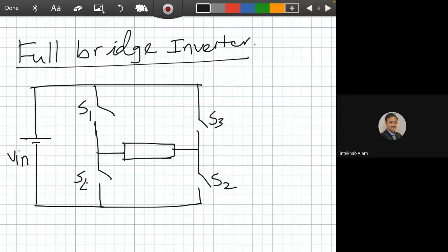The frequency here may be like 10 Hz, 50 Hz, 100 Hz, but in the chopper circuit, the frequency may be 0.01 Hz, each 10 seconds or something like this, or maybe more or less. Exact. Okay. In the chopper circuit, we'll close switch 1 and switch 2 for a long time, like 10 seconds, 20 seconds, and even minutes. But here, it will be in the order of milliseconds.